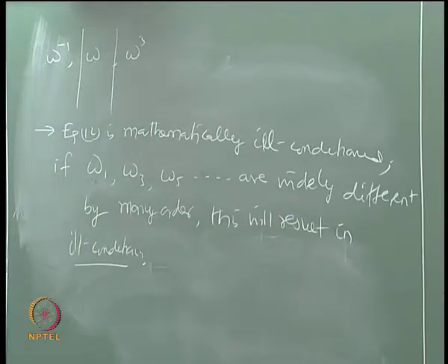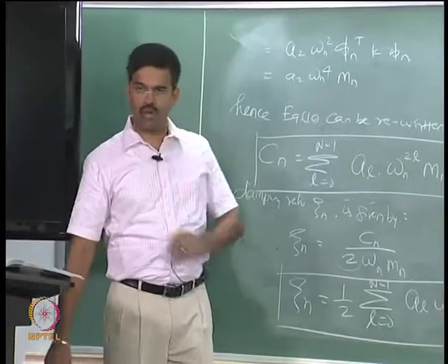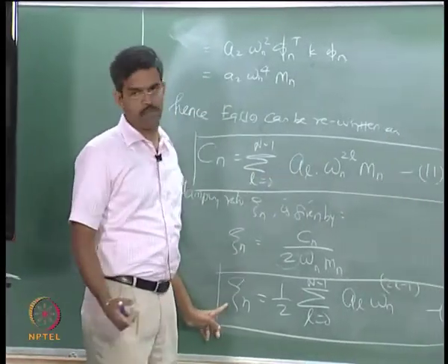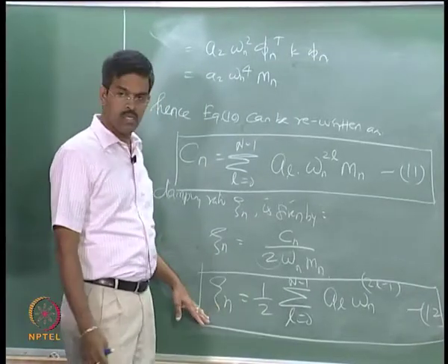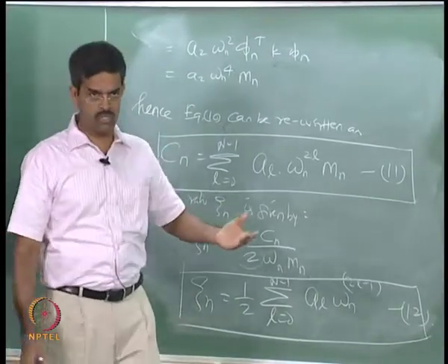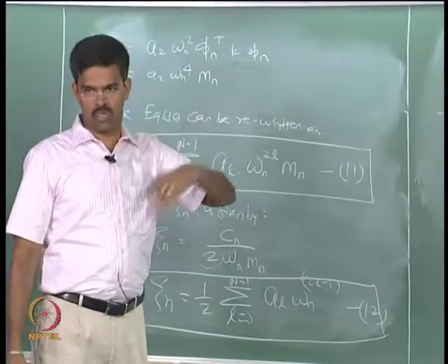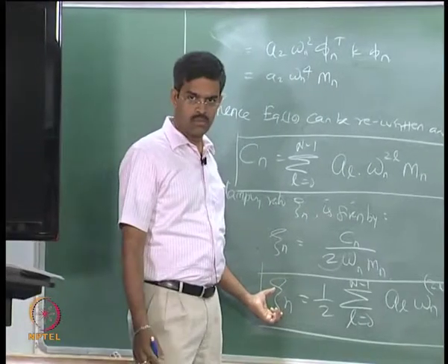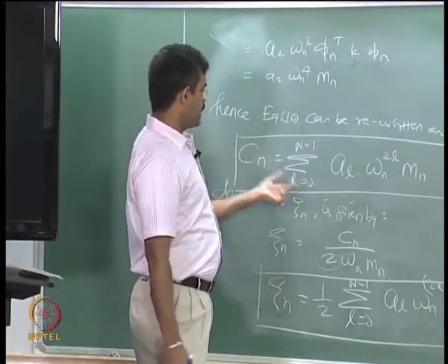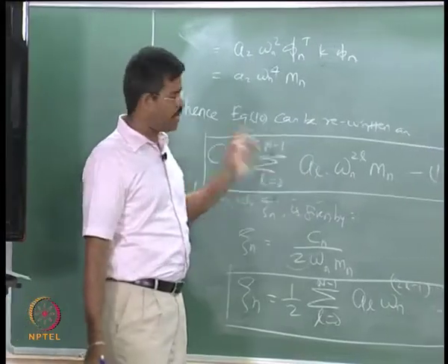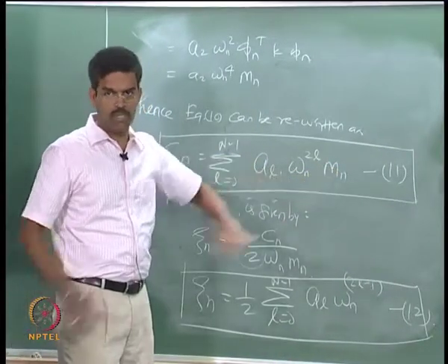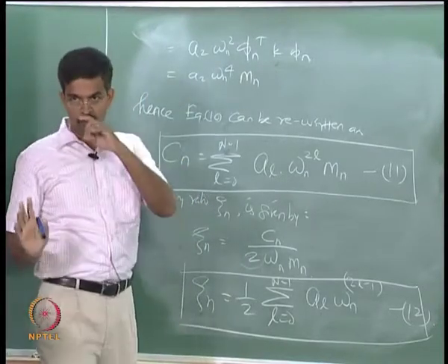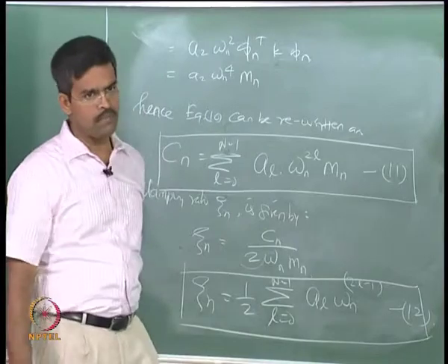That is the difficulty with this damping, but this damping is capable of covering all the frequencies as we saw, is it not? The damping ratios are skipped. See, I am not including the damping ratios of all modes, I am including only selective modes by order. Damping ratios are not included, okay. But here I can keep on adding from 0 to n − 1, I will have all frequencies included, but the damping ratio contribution from all frequencies are not coming in the zeta value, is it not? That is the problem here, okay.